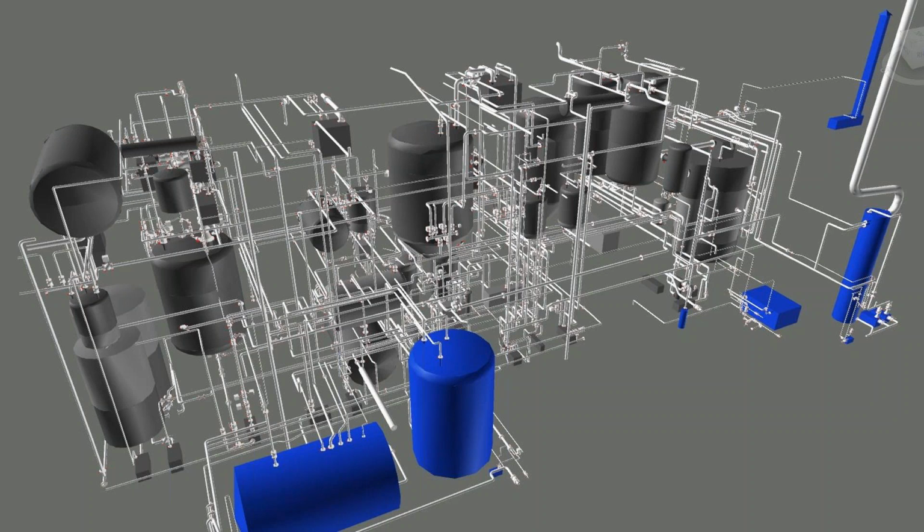They had plastic lines, stainless steel, carbon steel. They even had this unusual fiberglass one because they worked with a couple of nasty acids. They even had this carbon steel 150-pound flange spec. So it was a lot easier for us to just dump the Edgewise pipe straight into the project and then start converting it into the particular specs that we required.